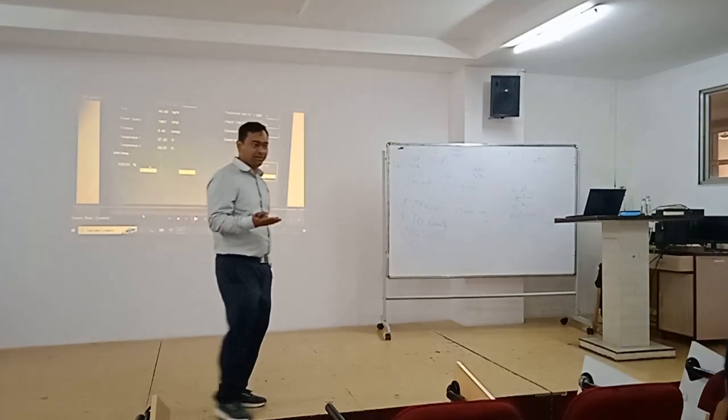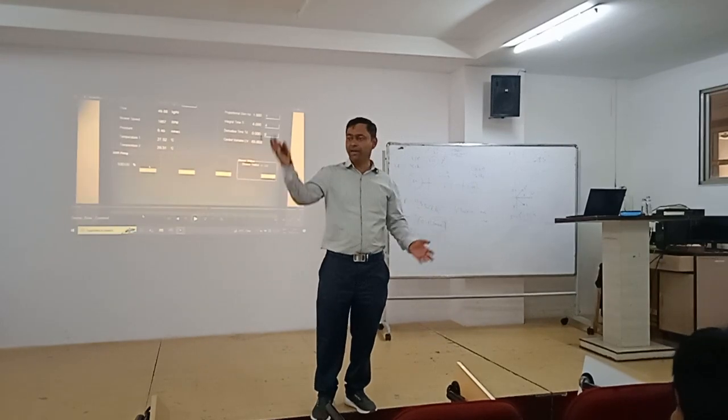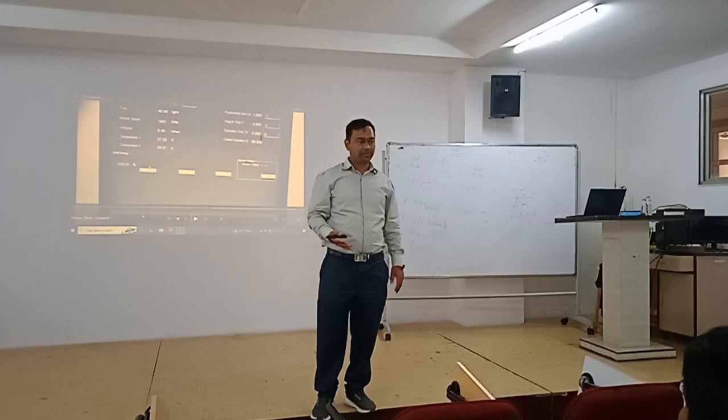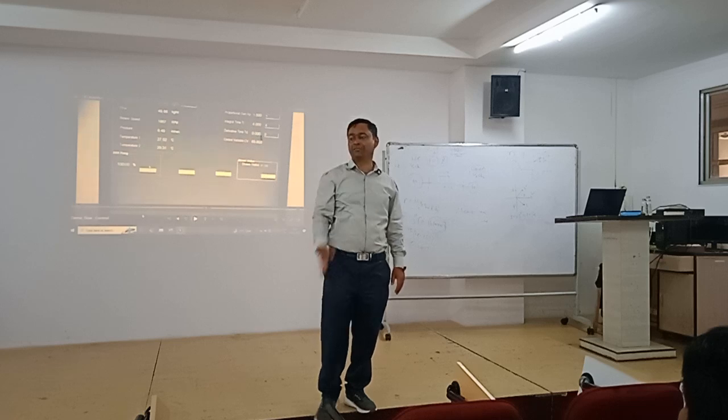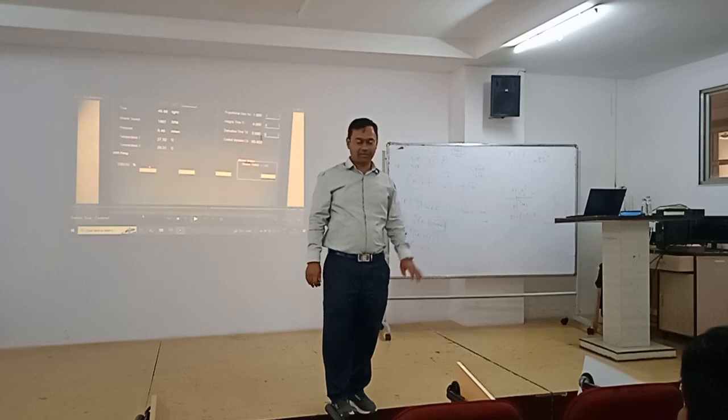Because it's air, right? So when you heat up the air, it's going to be lighter. Same fundamental we are using in a hot air balloon also. So when it's going to be lighter, your mass flow is going to decrease. So that's why the control system should increase that mass flow. So how can it increase the mass flow? I hope this is clear.